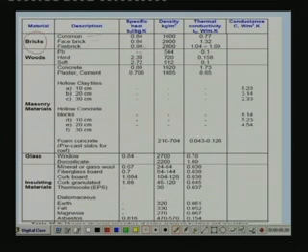For all these types of bricks, these are the specific heat values, these are the densities, and these are the thermal conductivity values. Since these materials are homogeneous, you need not give a conductance value, thermal conductivity is enough, and from the thickness of the brick and the thermal conductivity you can find out the resistance. Next come woods. You have plywood, hardwood, softwood, and these are the specific heat values and densities. Again these are the thermal conductivity values, because these are also homogeneous.